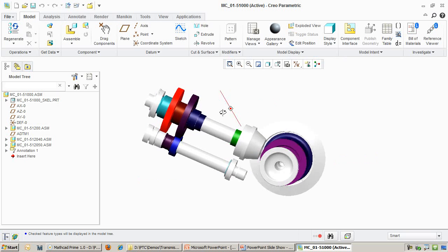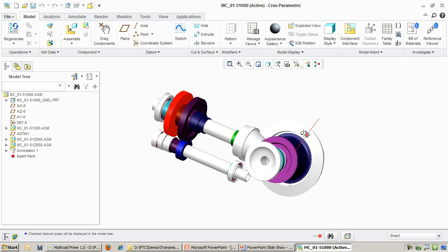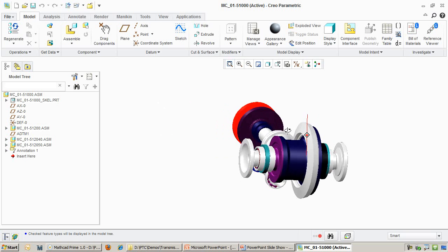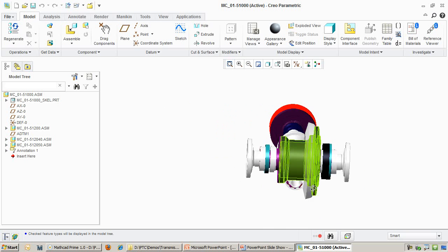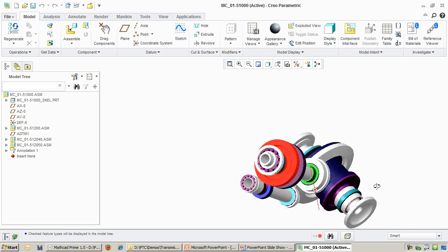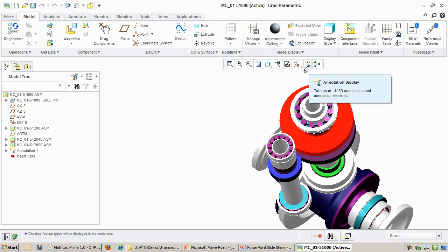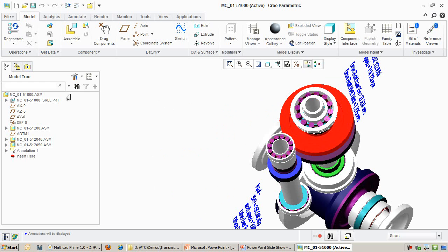In this particular gear, the driving gear has a radius of 23.5 millimeters, and the driven gear has a radius of 65.76 millimeters. We want the shaft to be able to deliver 250 horsepower of power while spinning at 2000 RPMs. We can put up some annotations to see the measurements we are dealing with.